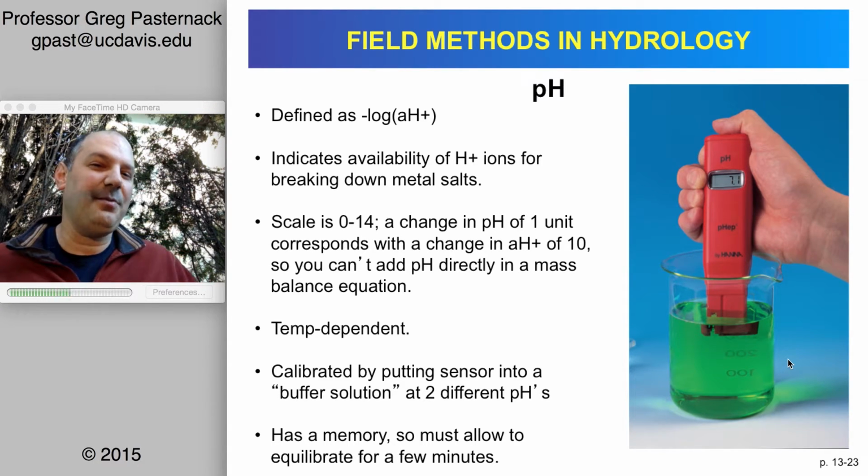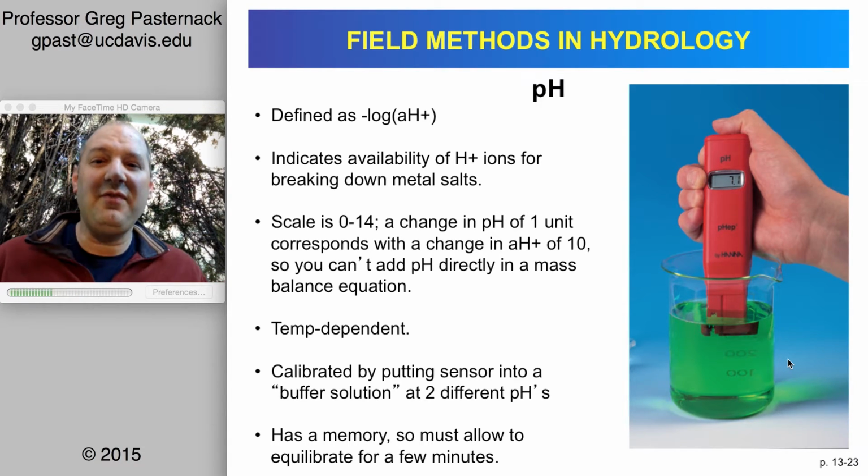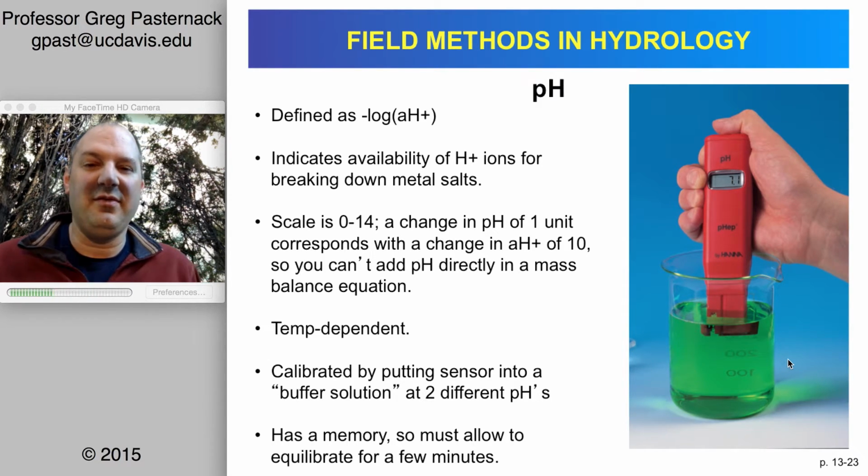If I take a sensor and put it in a pH 3 and then take it and put it in a pH 10, even if I try to wash it, what's going to happen is you still have so many hydrogen ions present, you're just overwhelming what's the actual condition. But it's pretty rare that you're going to make that extreme of a change.